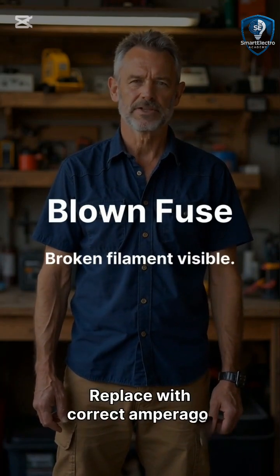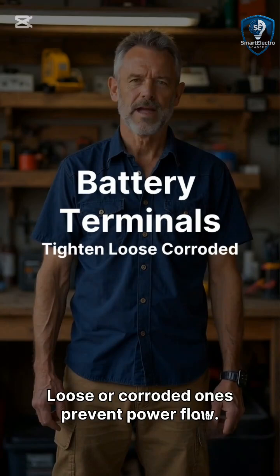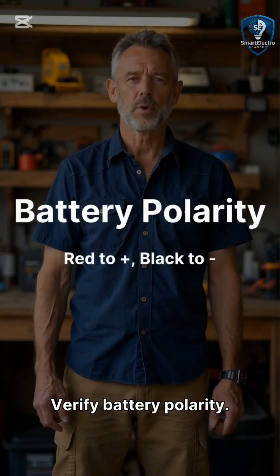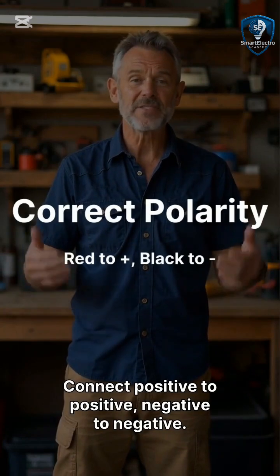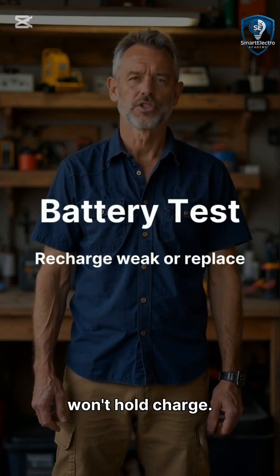Replace with correct amperage. Check terminal connections. Loose or corroded ones prevent power flow. Fasten cables securely and clean corrosion with a wire brush. Verify battery polarity. Wrong connections stop the inverter or damage it. Connect positive to positive, negative to negative. Recharge weak batteries or replace if they won't hold charge.